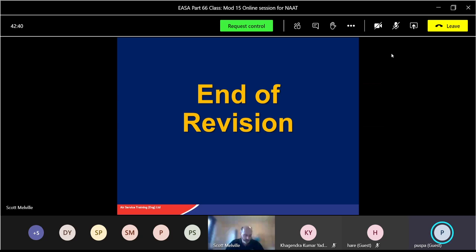Typical values when the sensor element is exposed to heat: we've got 3 heat ranges over a certain distance for the pneumatic type detector. I'll give you the first one. It's 250 degrees C over the total length of the element. Then we've got 2 more temperature ranges. What are the other temperature ranges?